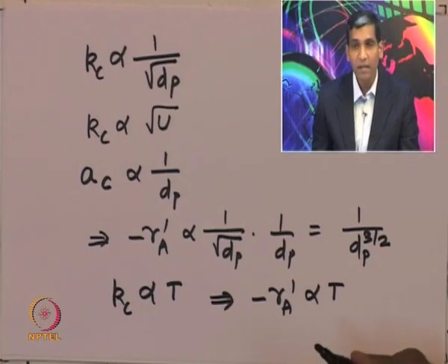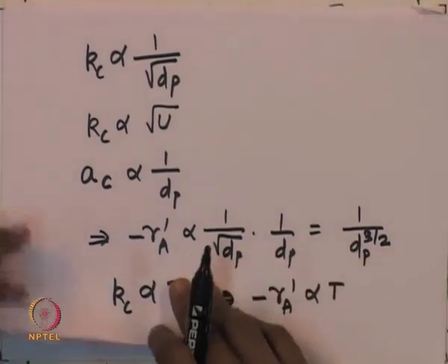What we have looked at in this lecture so far is the generalized criterion for determining, based on experimental data, whether internal diffusion controls the overall heterogeneous catalytic reaction. Then we looked at what happens if there is a network of first order reactions, and the general framework for finding the effectiveness factor and Thiele modulus of various species that participate in such a network. Then we initiated discussion on how to use experimental data to identify the various kinds of limitations and how the rate depends upon various system parameters. We will continue with this in the next lecture. Thank you.